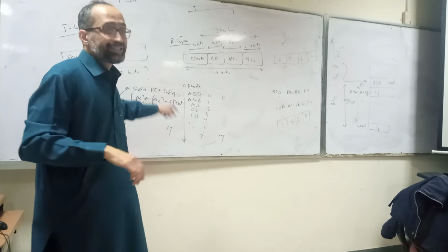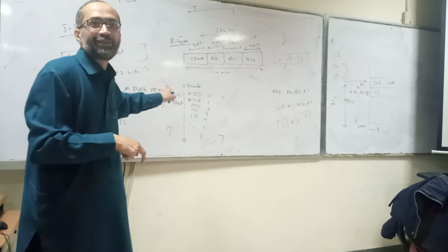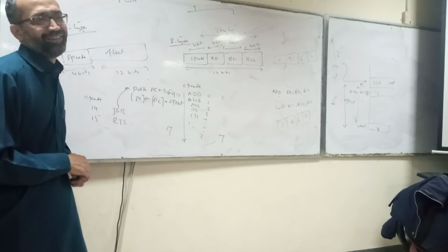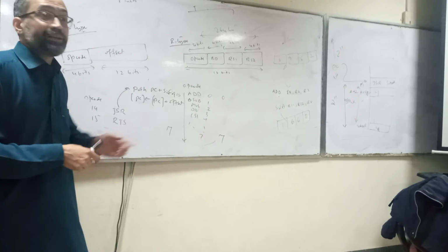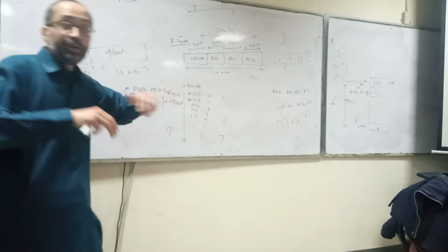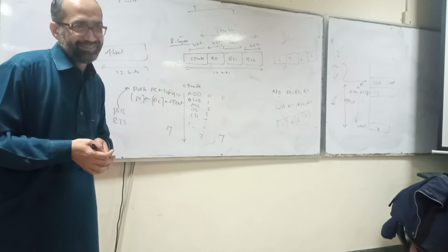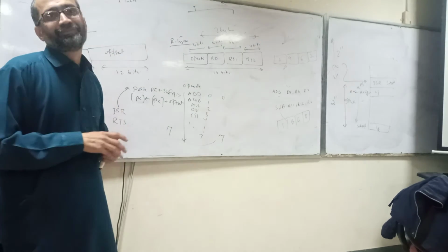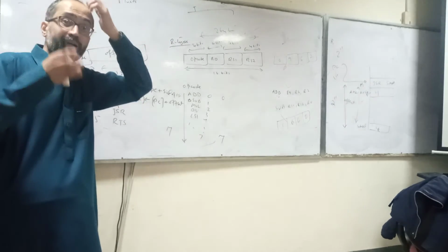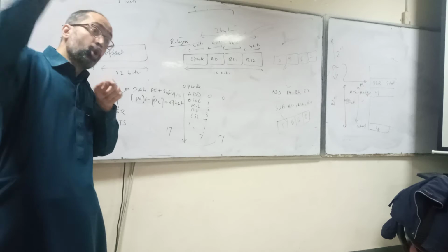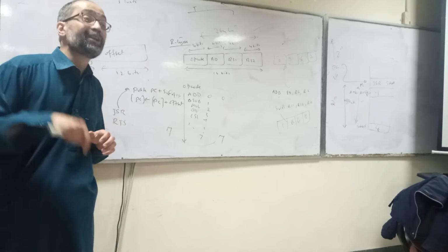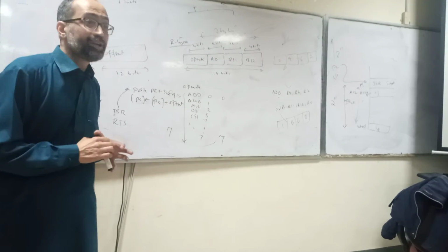This architecture is only supporting register addressing mode, immediate addressing mode, and 2 types of jump instruction, not unconditional jump instruction. Because if we support more and more addressing modes, it will be more complicated. That is reduced instruction set computing. In reduced instruction set computing, first you load the data to a register, perform operations on the register, then you store the data. So this is called a load store architecture.